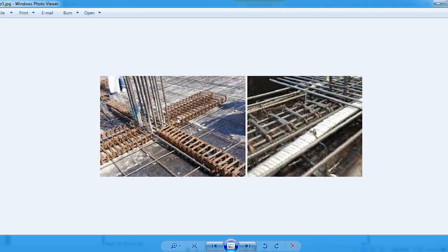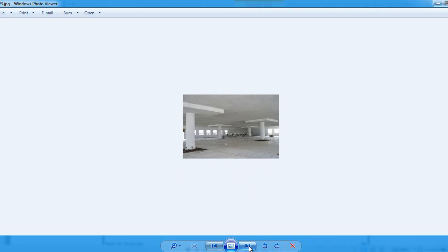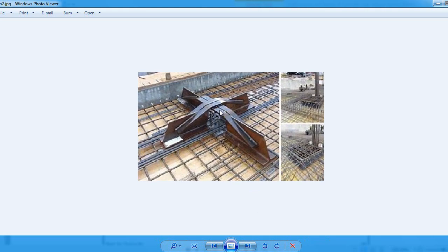Okay, you all know this principle in your beam design. And basically what we did, in the calculation, in lecture number 11 I will do an example on it. We determine the length of the horizontal bars, the area of these vertical stirrups, and the spacing of these stirrups, to control that kind of shear. And this is the way punching shear crack develops. You see the slab moving downward and the column upward. Here you see this is column capital, and drop panels I already explained, and this is also a drop panel, and this is known as shear studs.